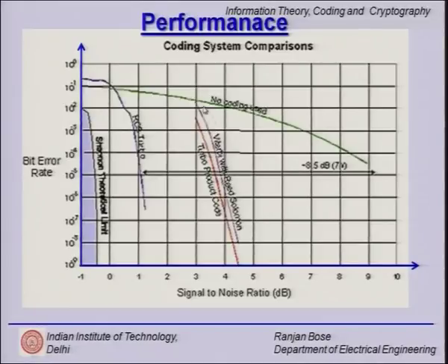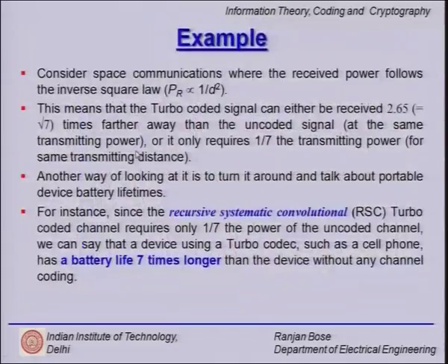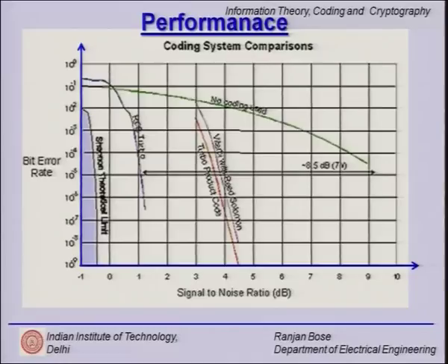As you can see, this x axis is SNR. So, Reed-Solomon codes work well at reasonably high SNR. Then if you look at turbo product codes, they are slightly here, but if you look at the recursive systematic convolutional turbo code, this is the performance curve for that. It really works at low SNR, and here is Shannon's limit, by the way.